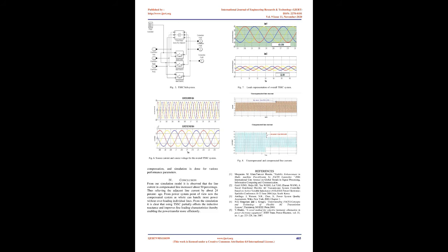This equation shows that the transmitted power can be considerably increased by series compensation, choosing a proper compensation factor s. The reactive power at the series source is given by Qcs = 2V²/(XL) · s/(1 - s)² · (1 - cos δ).